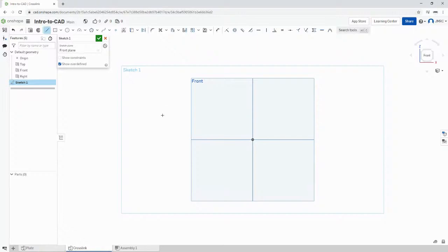Once more, I'm going to hit L. Let's create that line right away, committing to this horizontal line. Left click also. With lines, notice I performed a single click, so I created a chain of lines. Left click here, left click here.